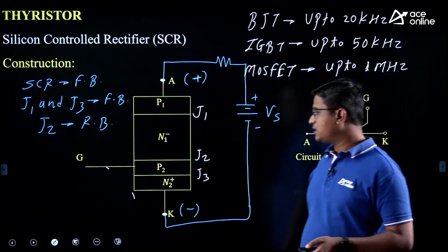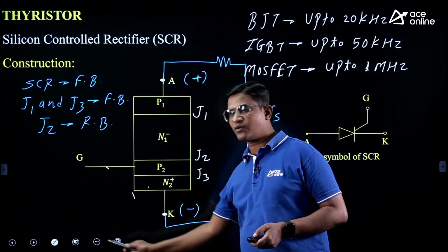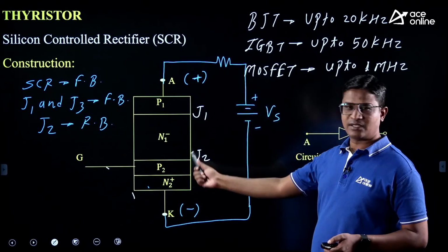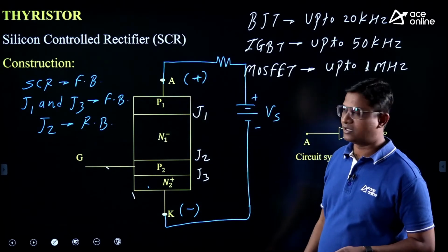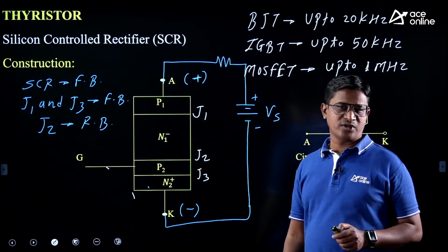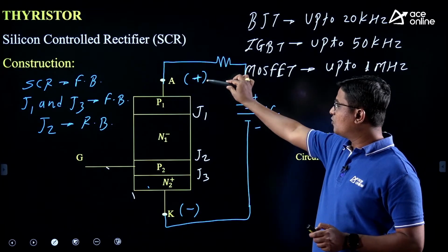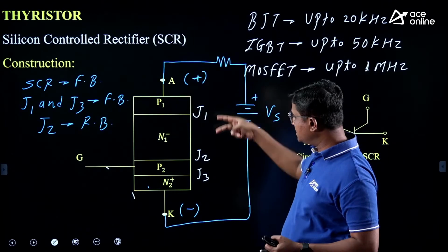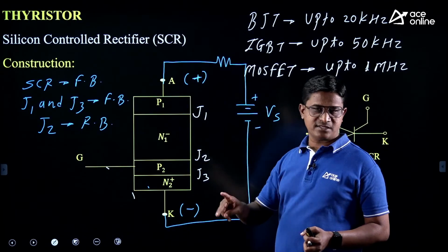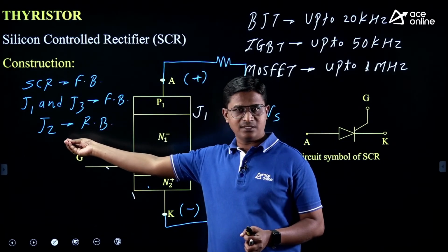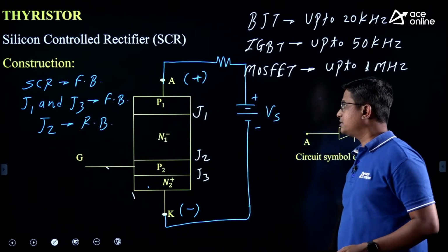So in order to turn on the SCR, what we are doing? We are circulating the gate current in this gate cathode circuitry. Okay, and my SCR will turn on. Right? Similarly, tell me, if SCR is in a reverse bias mode, SCR reverse bias means anode lower potential, cathode higher potential. Then your junctions J1, J3 reverse bias, J2 forward bias, completely opposite to that of this one. Okay, opposite to that of this one.